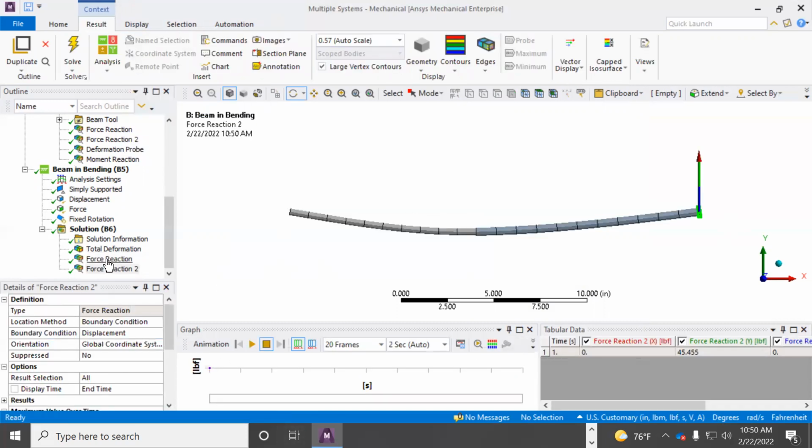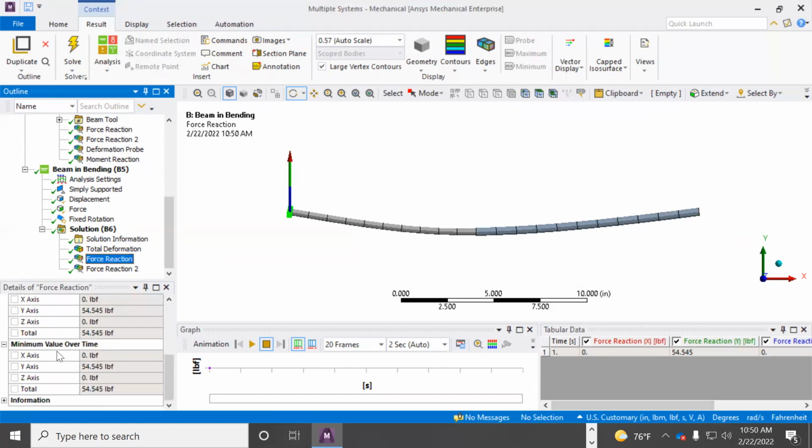And I'm going to look at the force to the right, going up as I expected, and look at the components. I'm getting 54.545 pounds upwards, which is what we would expect because the 100 pounds is applied closer to the right end. So A gets the bigger portion. Now, before looking at B, at the support at C, we're looking now at 45.4, right? So go to reaction here, 45.4. So this is how the numbers should make sense to us.